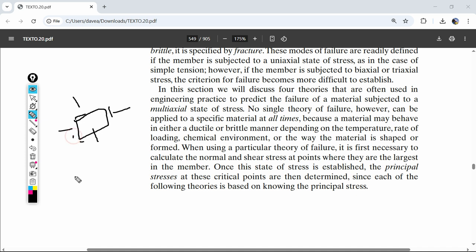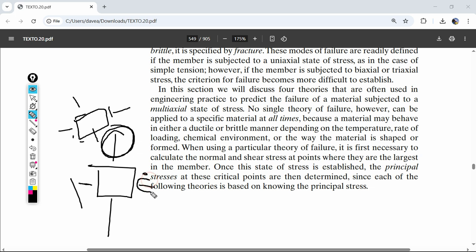Well, there's going to be some principal stresses where you rotate it to an angle, and either 2 of these are going to be big and the other 2 maybe not as big, but you're going to have no shear, and that's going to be the biggest stress you're going to get, and also the smallest or the opposite direction stress, and those are your principal stresses. And those are going to be in normal compression and tension.